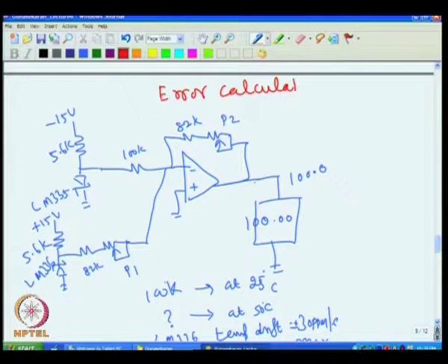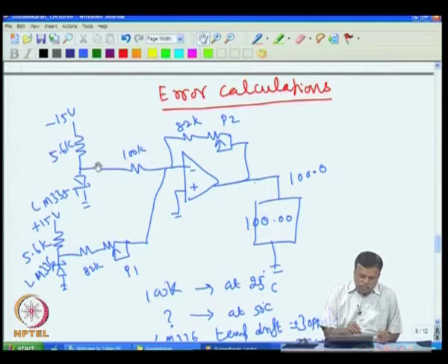or, as we generally call it in the analog domain, error budgeting, because error budgeting has to be done. This is the circuit that we used in the previous class. Here we used the LM335 as a temperature sensor, and the LM336 is a 2.5 volt reference zener. Since the LM335 gives 2.73 volt at 0 degree C, to compensate that we have put in the LM336, which gives 2.5 volt, and then we adjusted this resistance to make sure that at 0 degree C